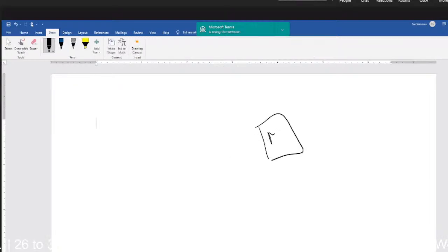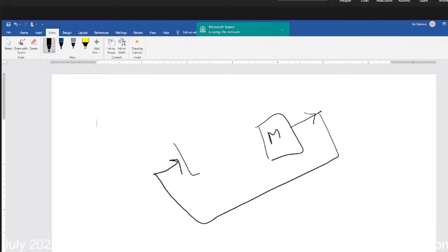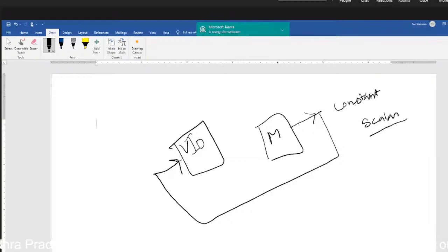So you have a module, right? It is giving an output. This output, I told you, you can connect to the virtual input of VIO to check it in the VIO interface. But if this output is a constant output, which does not vary with time, meaning it is just a scalar output, so initially it is something like 0, and after performing some operation you will get some value that is fixed, those kinds of outputs you can just observe in VIO.